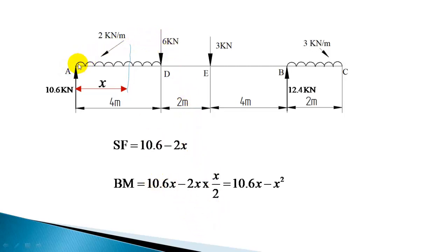The shear force is going to have a linear variation. It continuously decreases due to the downward UDL. It will always linearly decrease, so a straight line variation for shear force. And the bending moment, when you plot for this section, should be parabolic. Shear force for this section, immediately right of P, is 6, and it changes to 0, 6 to 0.